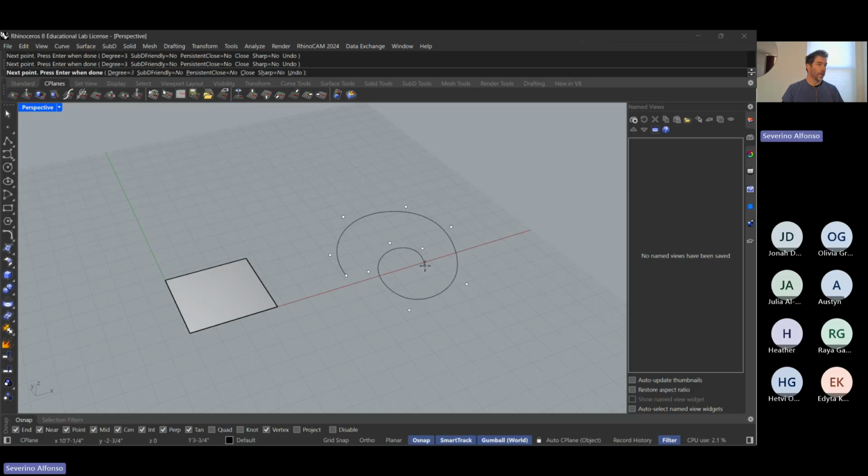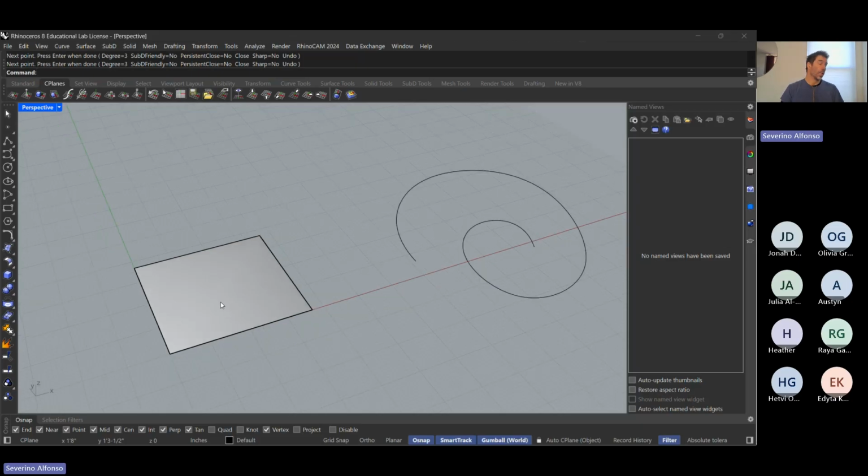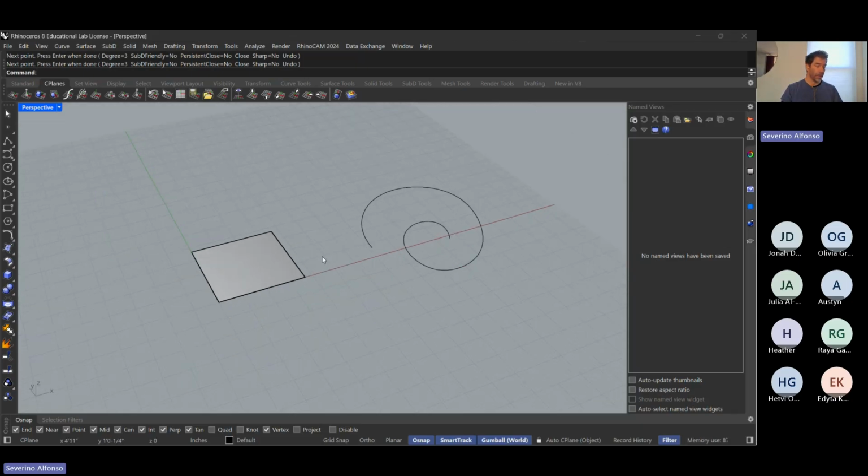And probably you've seen this in the past. You can redefine the number of points that defines a curve or a surface. That's called rebuilding. So rebuild, it's a command, and you can select curves, extrusions, or surfaces to rebuild. Just think of it as, I need more points so I can deform it in different ways.